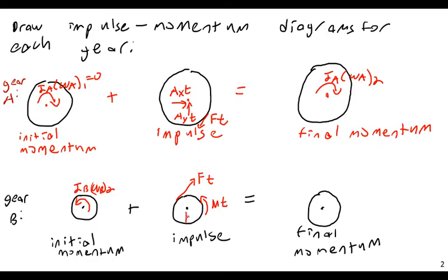And then we'll have the two reaction forces, BY times t and BX times t, although we know these are not going to contribute to the rotation because they pass through the axis of rotation. Trying to get those to produce any change in angular momentum would be like trying to push on a door by pushing on the hinge. Why do I add them if they're not going to make any change? For the sake of completion. I do want to draw all the forces on there, although we probably could ignore them, just like I don't have the weight on here. But anyway.